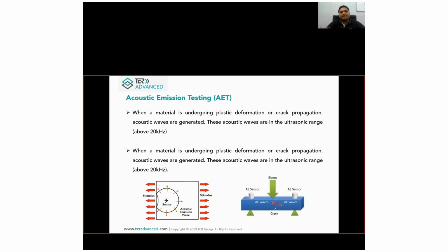This is a very advanced technique, acoustic emission. When the material is undergoing plastic deformation or crack propagation, acoustic waves are generated. These acoustic waves are in the range of 20 kilohertz. They are caught by the different sensors mounted on the component.